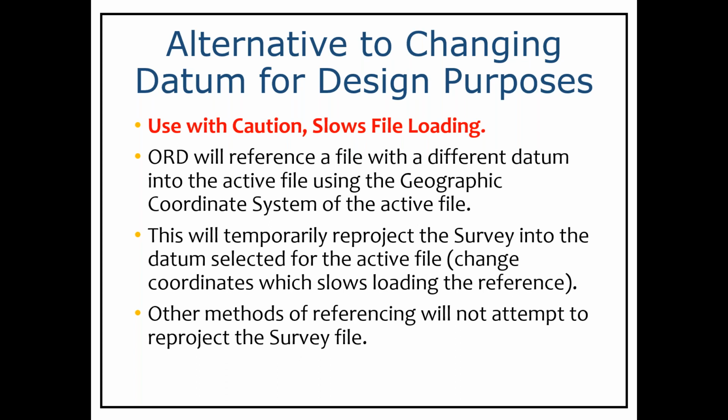But usually in ORD, when you select reference, there will be a pull down that says recommended. And if you choose that, you almost can't go wrong, okay? Because either it's going to match the datums or it's going to reproject it to the datum of the design itself.